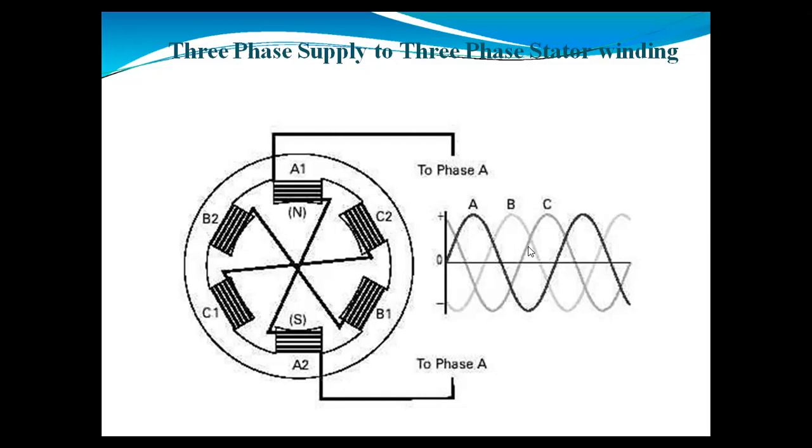So here, if we are deriving the value of current for R, that is A, you can write the equation. If you are writing the equation for current for that red phase, A phase, you can write IA or IR equal to maximum current Im into cos omega t.